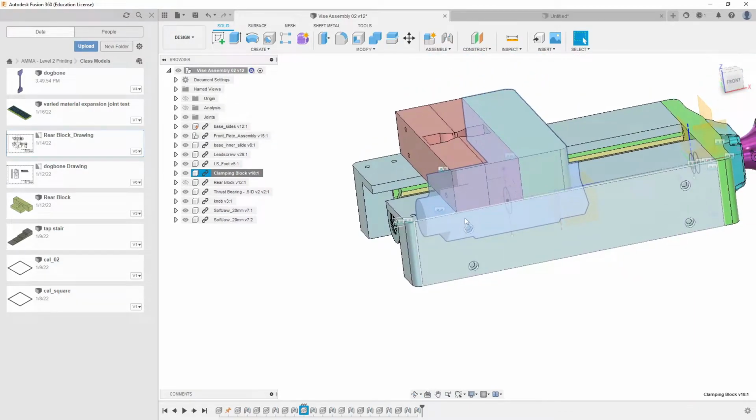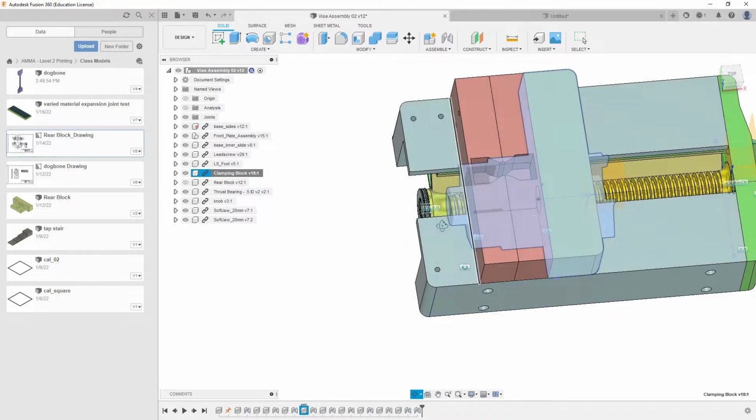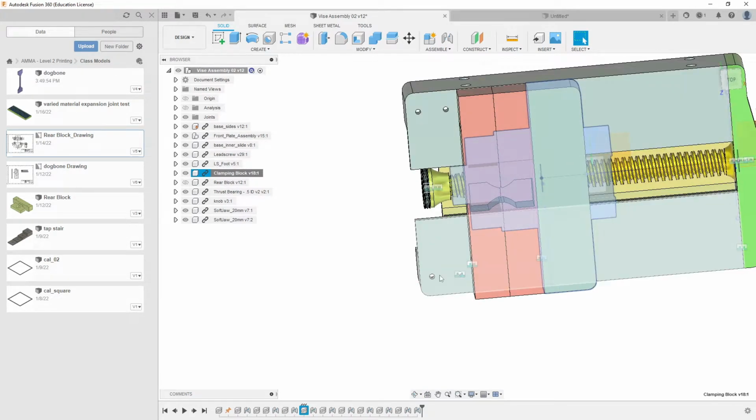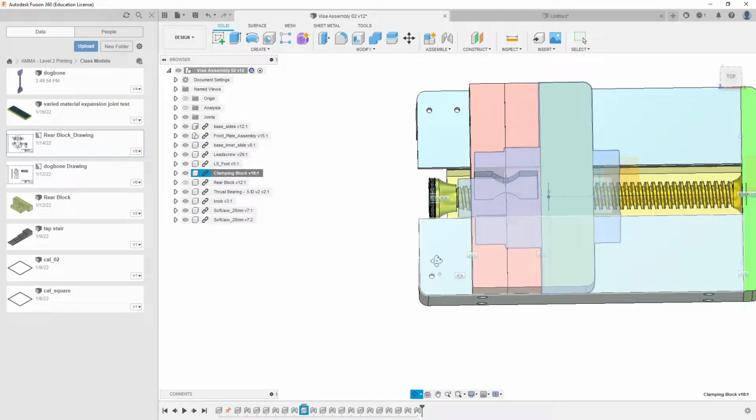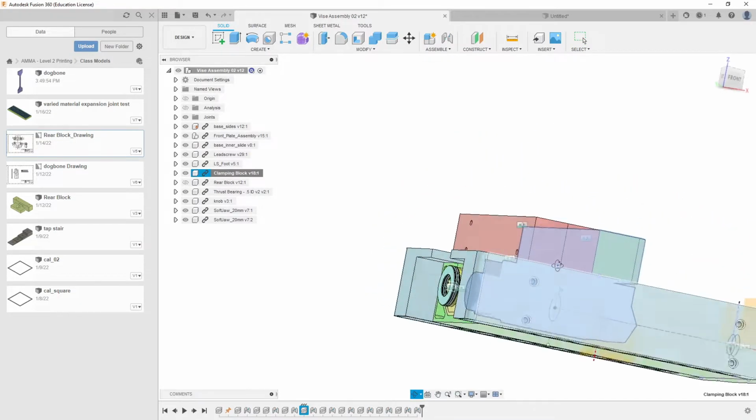And incidentally, that block sticking out, that might change in the future. There's conversation about the stability of this thing by making it longer like that. A good mill vise has a longer base on there so that this thing doesn't bend back and forth when you clamp something down. So that's a huge functional portion of a vise. But if it gets in the way, we might reduce it. Either way, though, when you look at this and you look at the back block that would be sitting here that I've got hidden right now, how far forward is this slide going to get to that before it runs out of, you know, track to run on? So it's not perfect, but that's kind of the thoughts I was thinking.